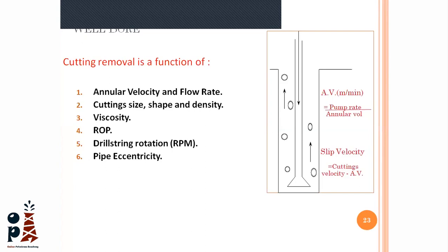For example, guys, if you go to the rig or read about drilling operations, for the surface section we use a mud called spud mud. This mud is just bentonite and water, providing the required viscosity to help clean the well.